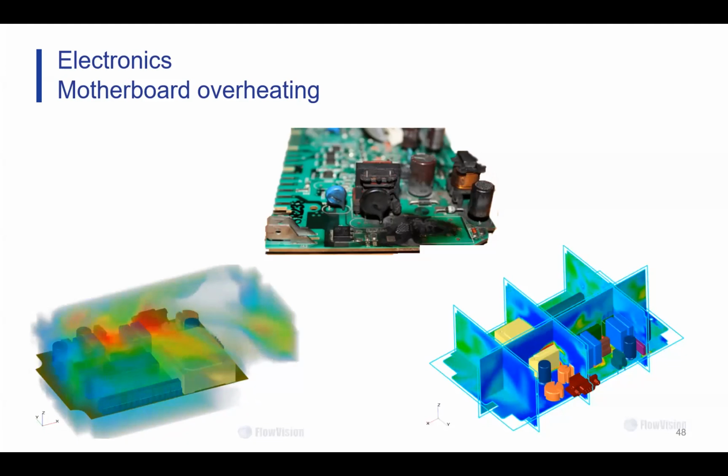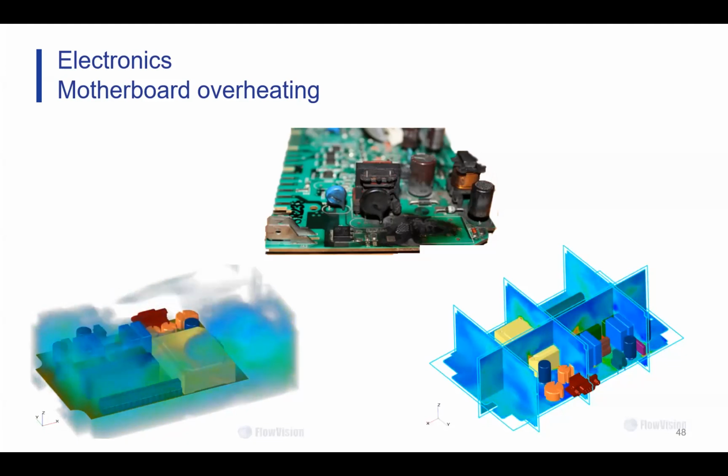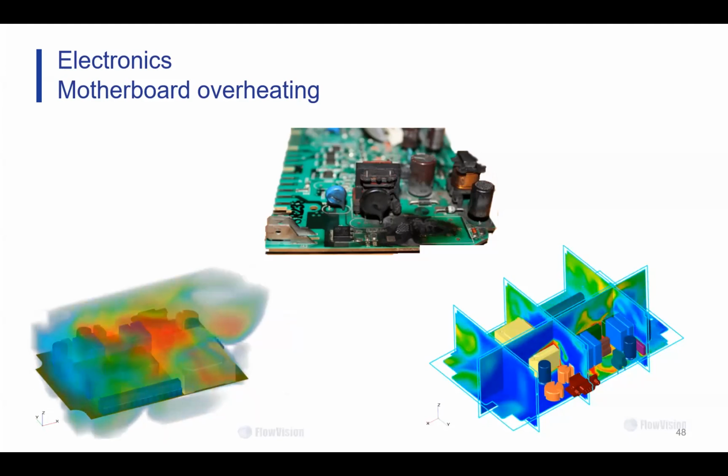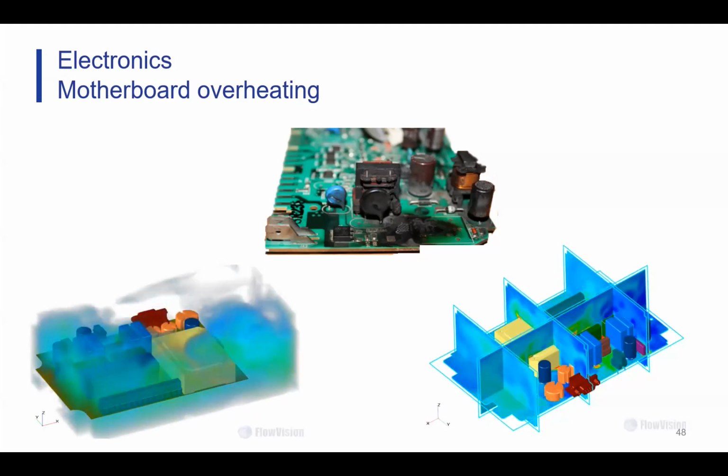We basically create small surface offsets between the regions, move them slightly apart, and then use that gap model, that clearance model, to simulate thermal resistance, simulate bridging.